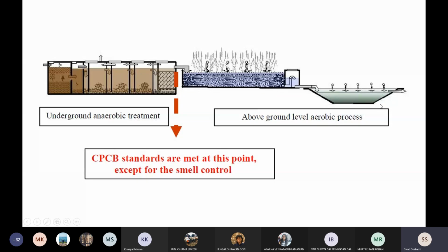Okay, and then that water can be used for the larger irrigation system. But these ponds can also be lined with some kind of stone pitching, so that the soil mixing is not happening. So it can be an open pond in that sense, so that your oxidation process happens, and then it can be taken for the various uses that you might need. Is that clear?